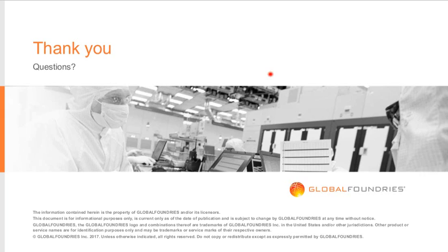And next question, are there on-chip capacitors offered in the 45 RF SOI? Yes. For 45 SOI, we provide different types of capacitor. The cheap solution is the VN cap, basically a single metal-to-metal layer capacitor. And also, we provide two kinds of MIM capacitor. One is called high-density MIM cap. Another one is called high-Q MIM cap.